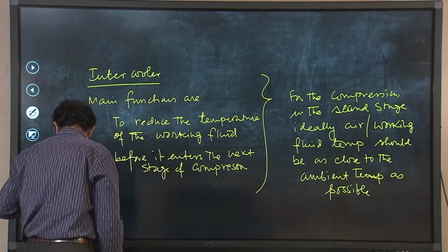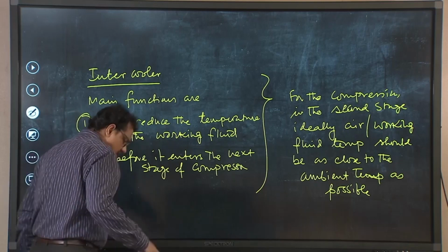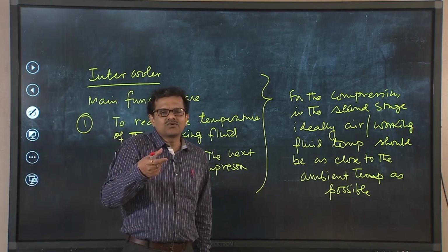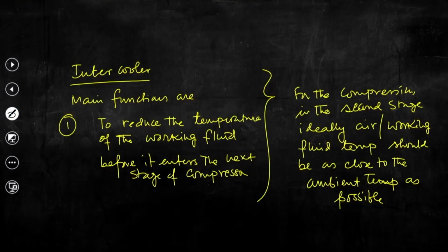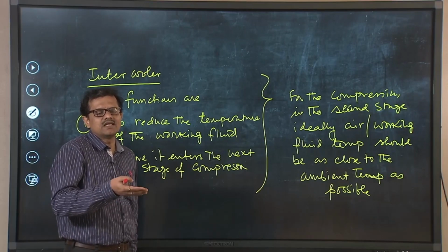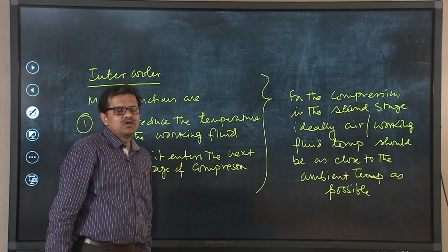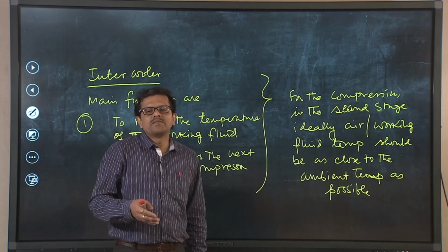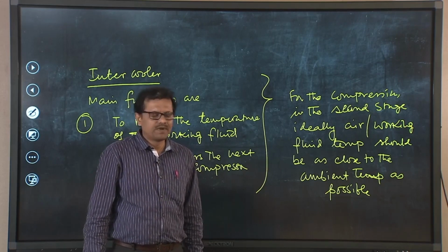And the second thing, as I said, it is easier to compress cold, heavier air than hot air. If temperature increases beyond a threshold value, then that high temperature will be very difficult to handle by several mechanical components inside the compressor.